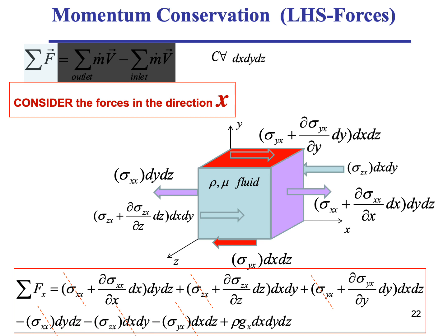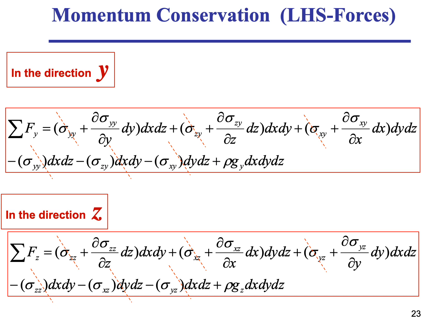So these are the things that don't change. We don't care about things that don't change. They come in and leave and they don't do anything. We only care about the change itself, and that change itself is what creates these forces, the internal forces between my fluid elements. And then we do the same thing for the y direction. So the second index is y, sigma zy, and sigma xy, and do it for the z direction.